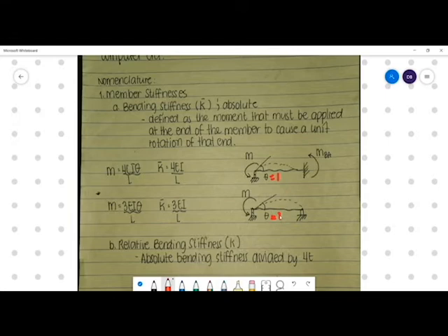I think we are able to solve that using what we've learned from our Theory 1, on how to solve for deflections. Either you try direct integration, area moment, conjugate beam, or virtual work. From that, we are able to get the value of theta, and then we express the moment in terms of the theta that we solve.